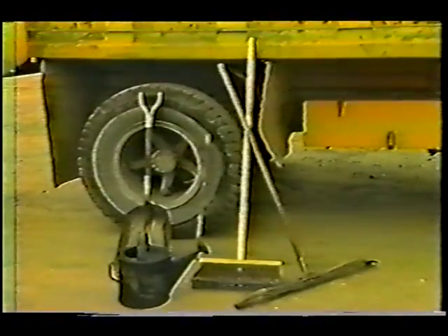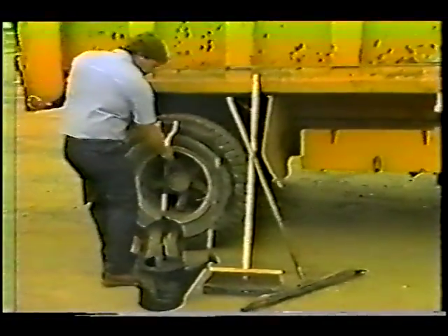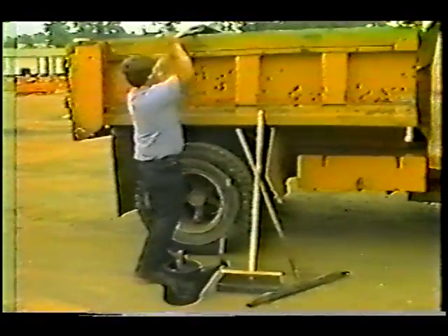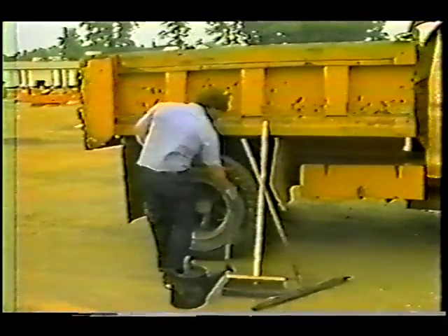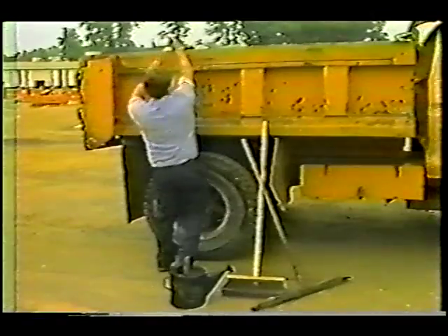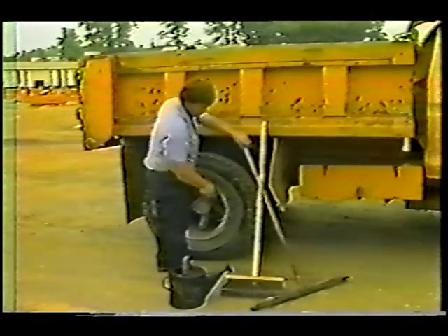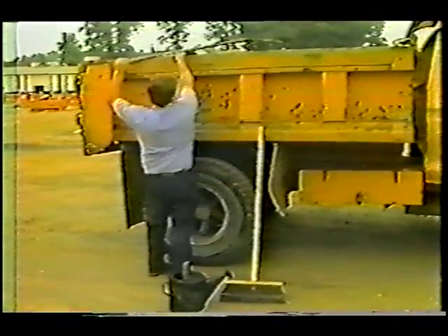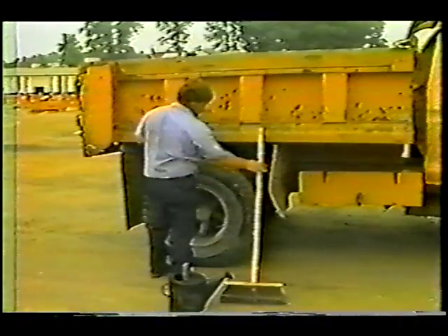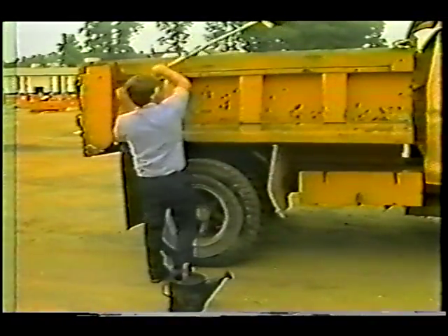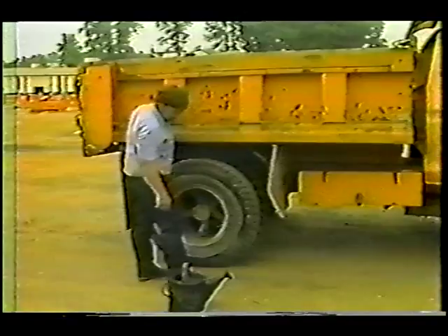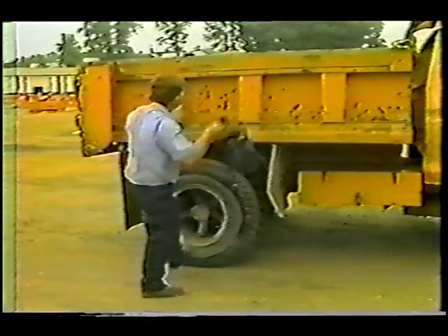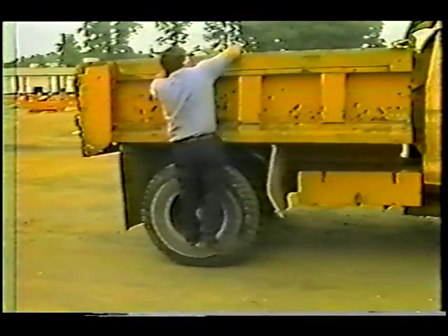To repair linear and area cracks, you will need hand tools and equipment designed to do the job best. The proper hand tools include narrow and wide squeegees, a sharp-pointed rod, a rake, stiff brooms, shovels, and a pouring pot for the asphalt mixture.